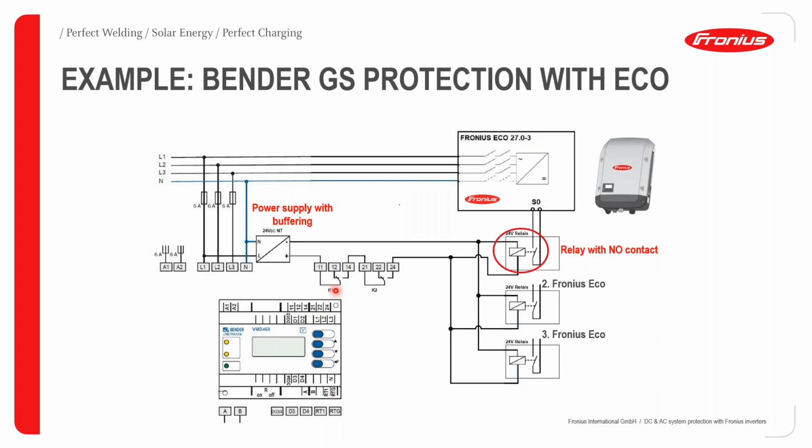So as you can see in this case, basically all relays or all contacts have 3 terminals. So they're usually the common point, the normally open contact, and then the normally closed contact. So for this protection scheme, the normally closed contact is being used. So as you can see, terminal 11 is connected to terminal 12, which is the normally closed contact.